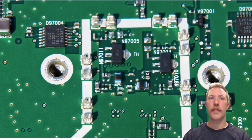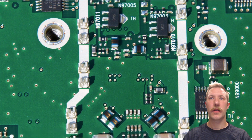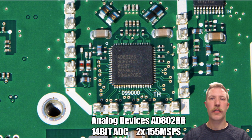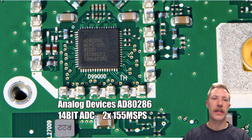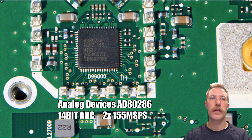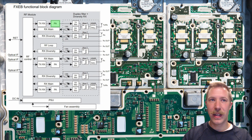It doesn't really contain that much. There are a few switches for power supply, but otherwise all the data lines and so on are routed down through the layers of the board. So all we can really see here is that we have an Analog Devices 14-bit ADC with 2 times 155 megasamples per second bandwidth, and this is what is feeding data from the converted analog signal back into the protocol conversion CPUs. The power amplifier, finally.